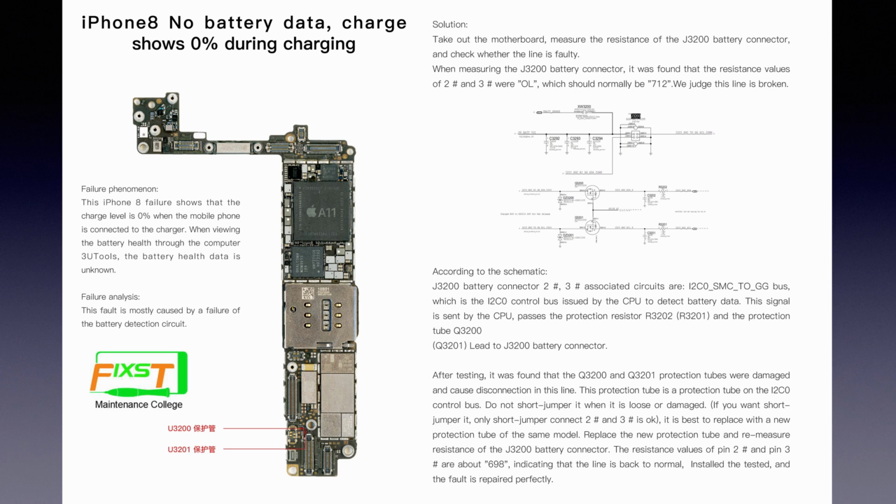After we replace a new protection tube and test the connector again, the resistance comes back to normal. So we install and test the phone. The problem has been fixed.